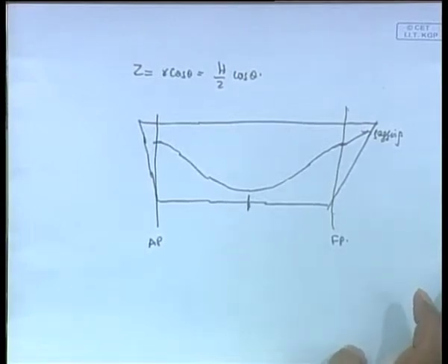Right now, what do we have? We have the profile of the wave superimposed on the total length of the ship. That is one of the important things in doing this. So now you have the wave profile, and based on this we can calculate the longitudinal bending moment.